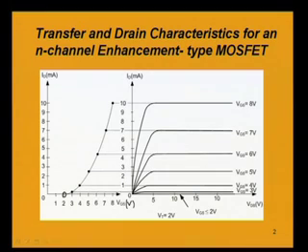That plot can be obtained by joining all the points whose coordinates are VGS and ID. So, in this drain characteristic, the saturation current is just extended and the intersecting point between this saturating current and the corresponding gate to source voltage is that point which we have to obtain.